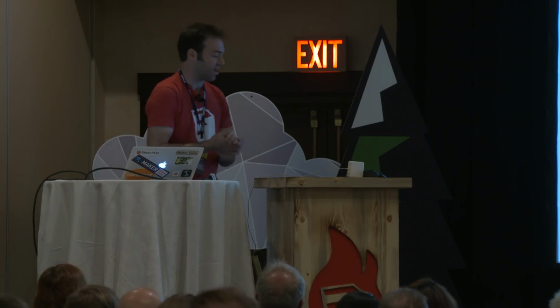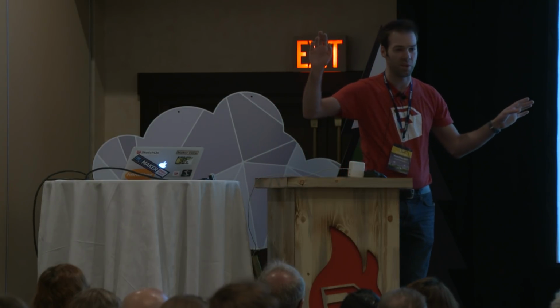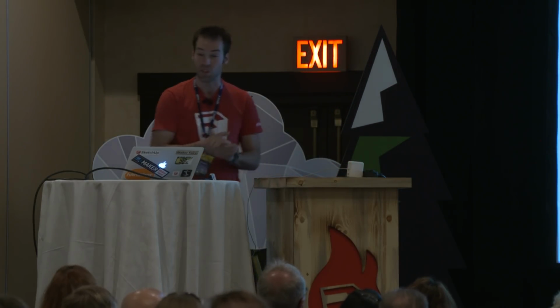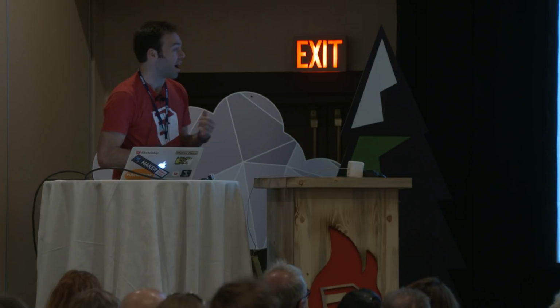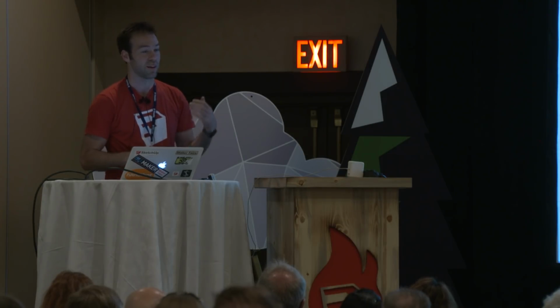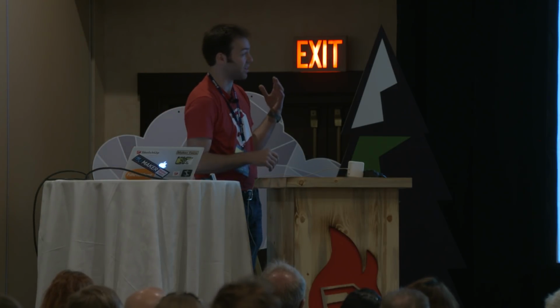But before I trace it, how many people who have traced floor plans like this before have traced it off of an image, and then you end up getting wall dimensions that are like 47 and 1/64 wide? So there's a way to fix that too. You could trace all of your walls, go back, check all the dimensions and do push-pull to fix it afterwards, but that's a little bit tedious. I like to fix it beforehand.